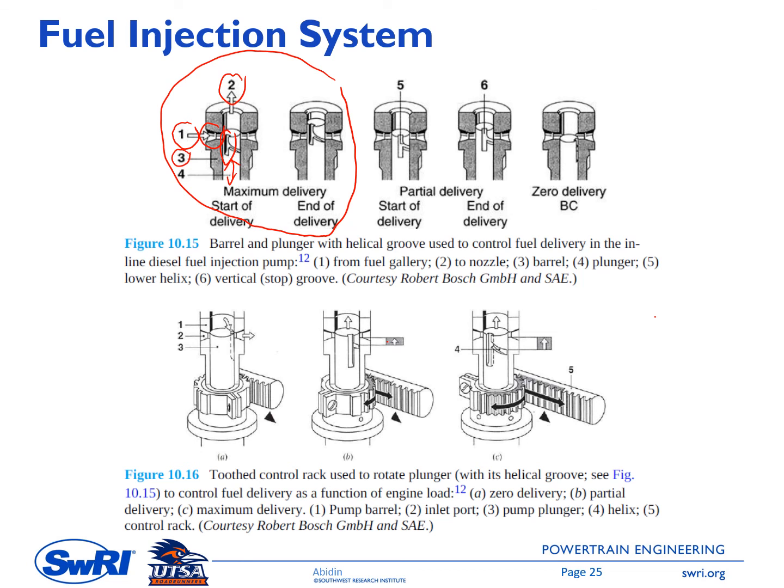In the next one, you can see that the groove at the plunger is at a different position relative to the nozzle entrance here. So this is the condition where we have partial delivery. In this case, the fuel is still flowing from the left. Some of the fuel will move up, flowing into the nozzle, and some of the fuel will move to the right.